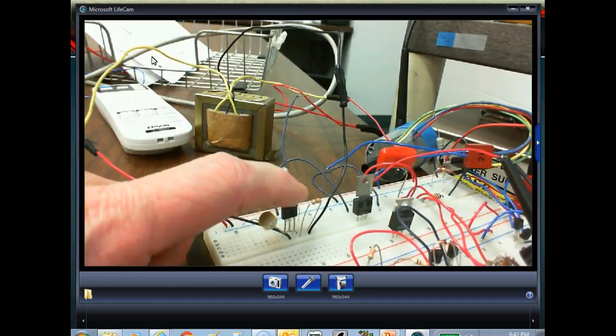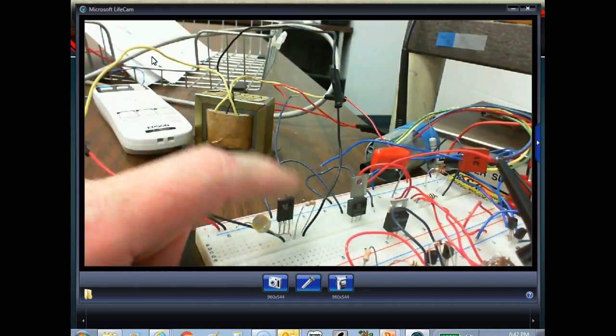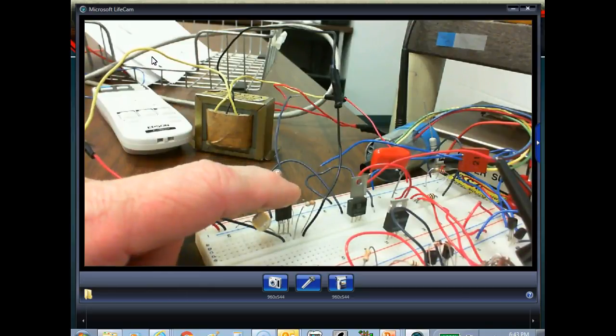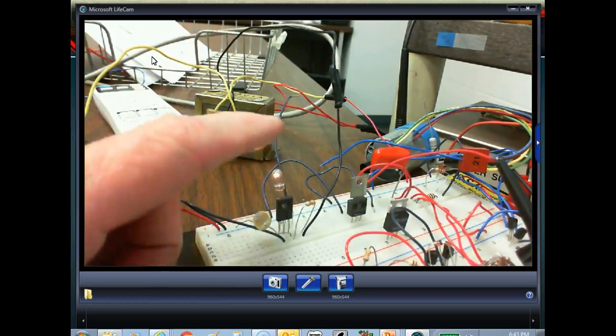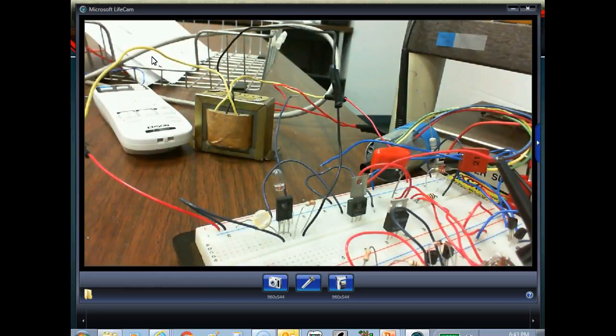Oh, by the way, PLCs use these guys here too. If you got an AC output module on a PLC, it's got a triac. That's what it fires the output with. If you got a DC output module, it's going to use a transistor, but on a PLC DC output module, the transistor is either saturated or it's off, so they're using it like a switch, right?